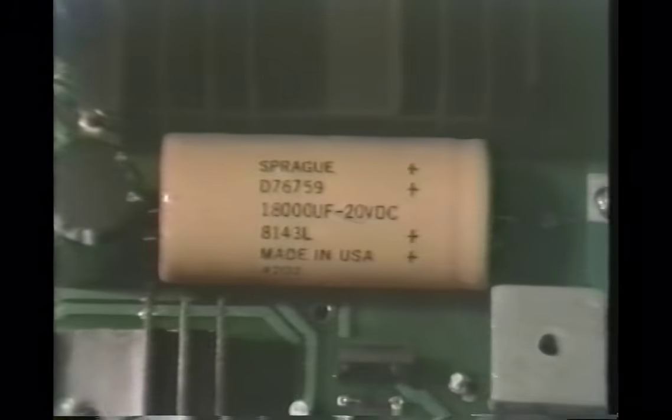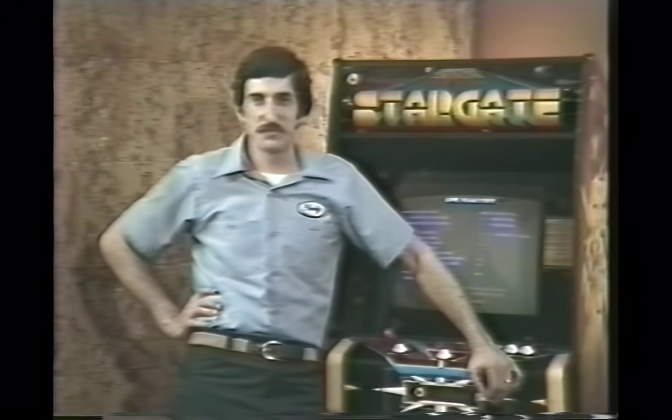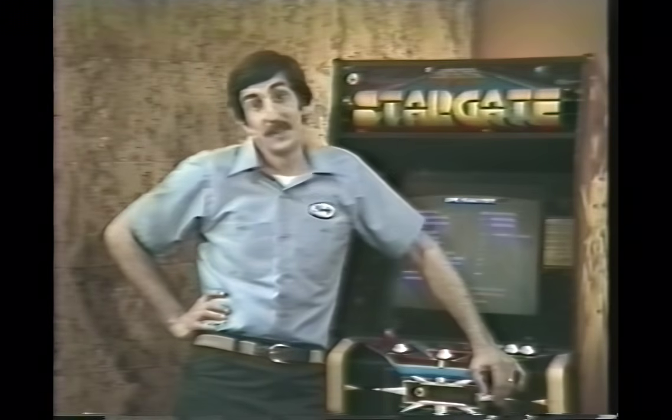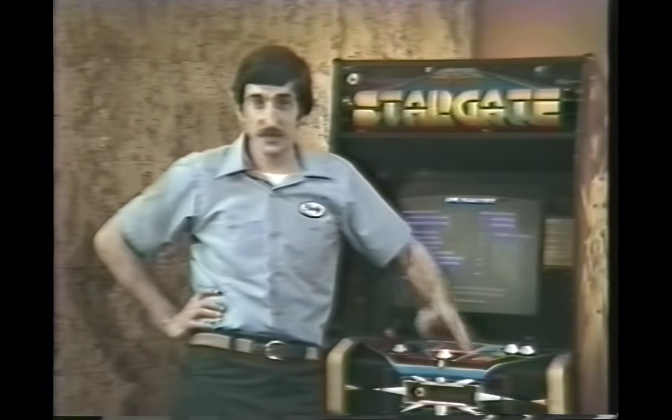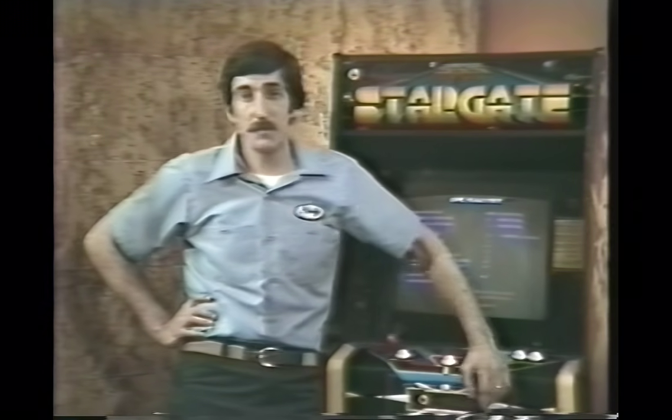This Williams power supply has two typical filter capacitors. This one's 18,000 microfarads, 20 volts, and this one is 4,700 microfarads, 35 volts. Well, when you go to a local electronics store to get a replacement capacitor, chances are not overwhelmingly good that you'll get an exact replacement. But you can get a capacitor that'll do the job for you.